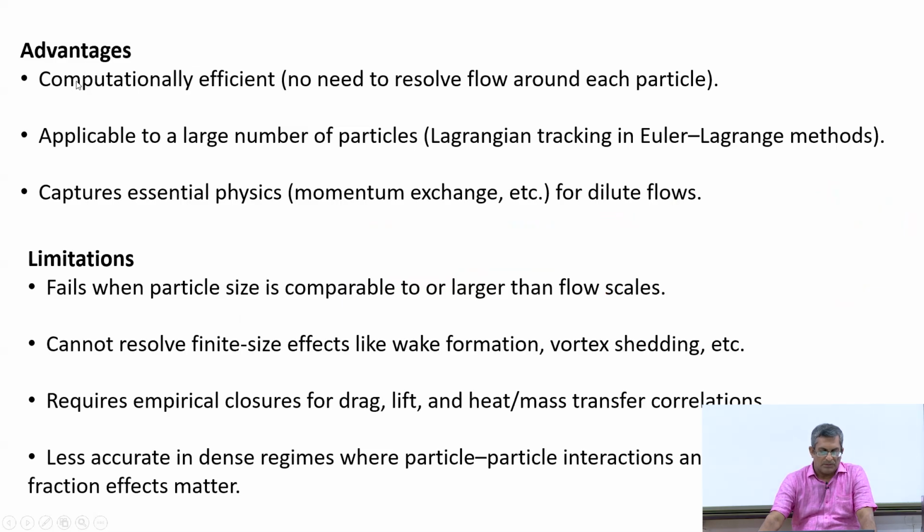The main advantage here is that it is computationally efficient. Why? Because we do not have to resolve the flow around particles. Then it is applicable to a large number of particles so that we can deal with engineering types of problems. And this facilitates simulation of the particle-laden flow in the Eulerian-Lagrangian framework.